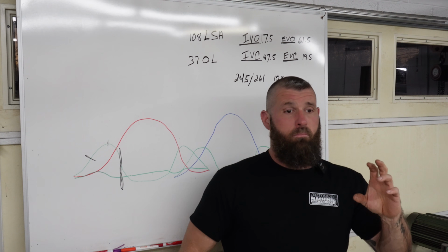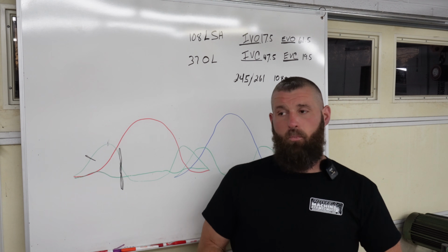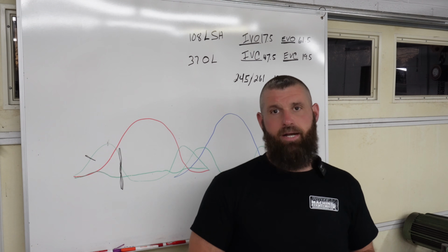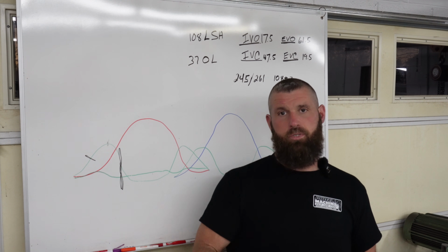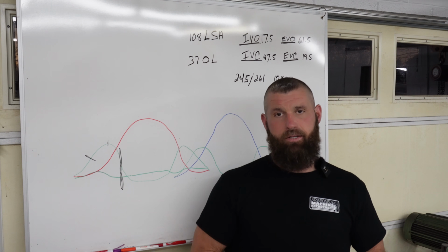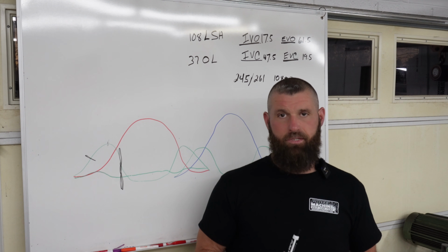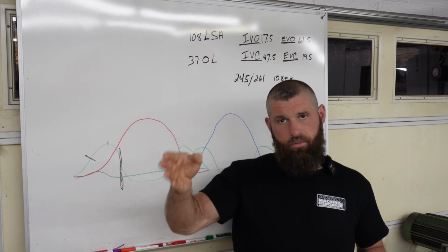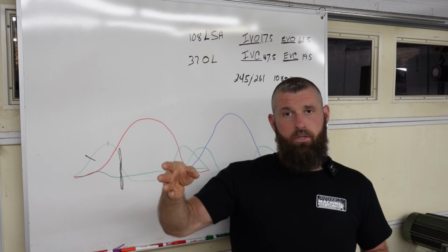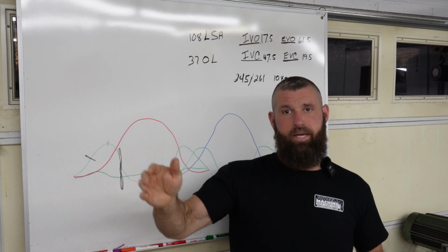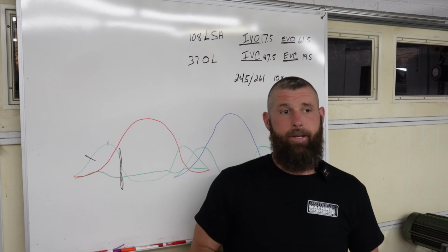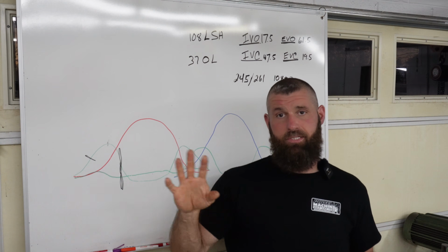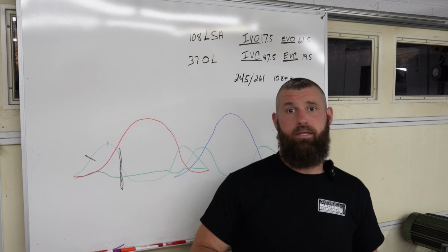So many of these people, we've had it multiple times in the last week. A lot of this drag and drive stuff. People got 427 small block Chevrolets and they got a 290 or a 300 CFM cylinder head. And I'm just like, man, you're killing yourself. If you'd have bought this part number head, you would be way ahead of the game than this head. And so we've had a couple of people like, man, I need to back up and see if I can send these heads back and get the right head.